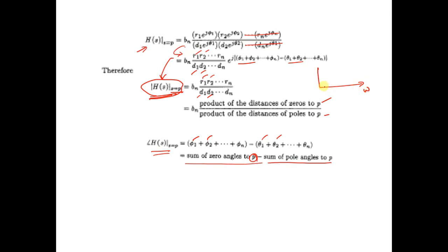At different points, you will be getting different modulus of H(s). So you will be getting some points like this, and likewise you will be getting the amplitude response. The amplitude response is nothing but modulus of H(s) versus omega. When you plot modulus of H(s) versus omega, you get the amplitude response. Similarly, if it is the phase angle, then you get the phase response of the filter.